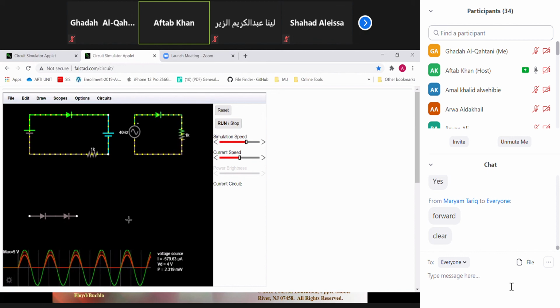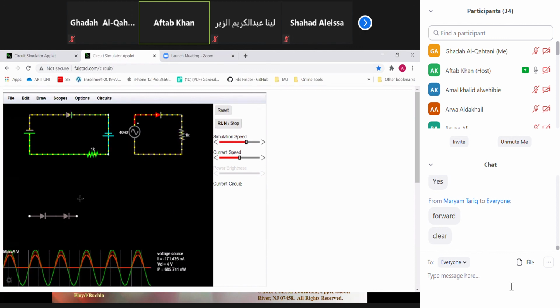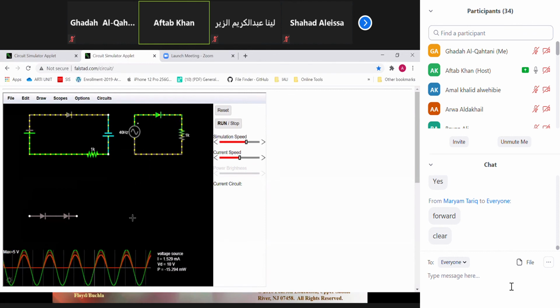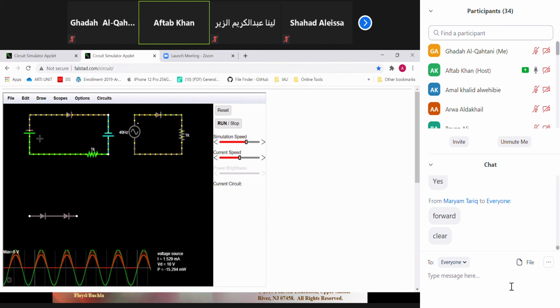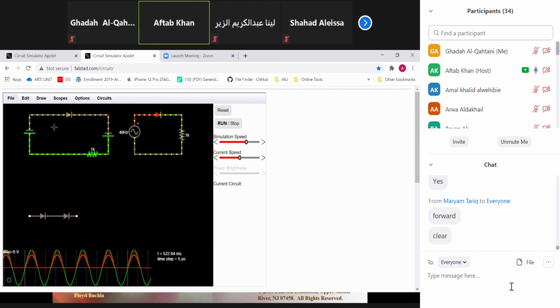Current is moving. Now I'll do one thing. I'll make it negative now, swapping the negatives. Now I will make it -8 volt as I said there, and I already reversed the polarity and made the other -10. Same example which I just gave. See now, conducting, current is flowing. The reason? Because it is -8, but this is -10. So the anode is connected to the more positive terminal with respect to the cathode. That's why. This is the concept of this one.